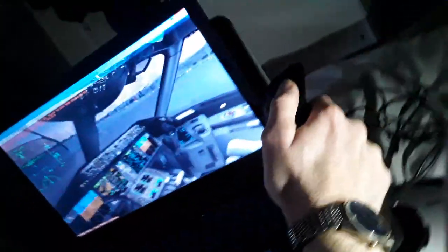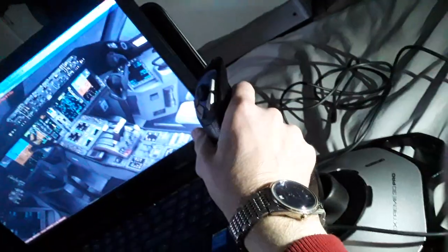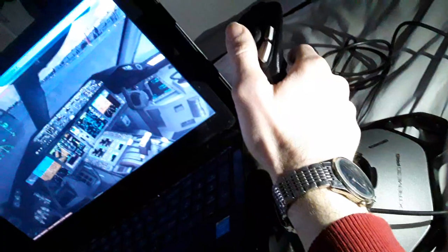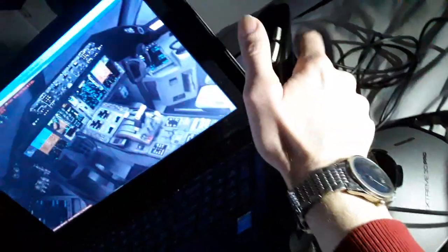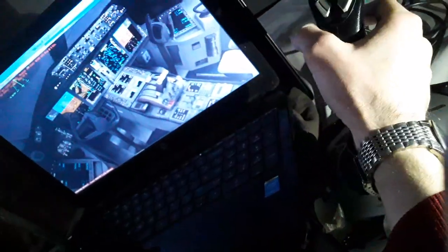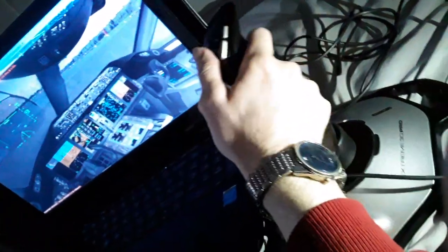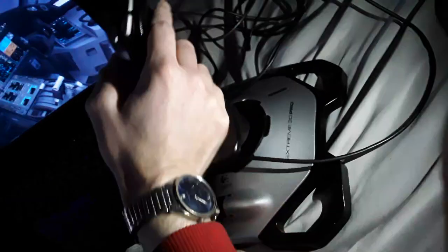So turns to the right in the Airbus, you remember, is limited. Some degrees deflection, or G's, 67 degrees. So you see the Boeing is similar in controls, left and right turns. The deflection of the control wheel over here is identical to the Airbus aircraft. Also the climb and descent, the control wheel input of the Boeing, or the side stick back and forth of the Airbus, like this.